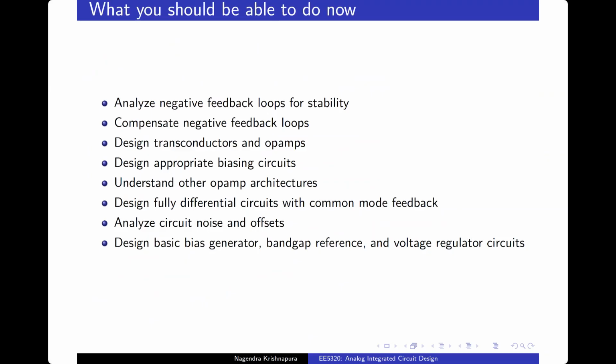Right, right. So if the threshold voltage is varying with signal and it is significant, then you have to go to nonlinear analysis or more likely simulation to find out what's happening, right? But the main objective of all these design principles and calculations is to see in which direction to steer your design, not necessarily to calculate to the third decimal what the swing limit is. Swing limit itself is such a crude measure, right?